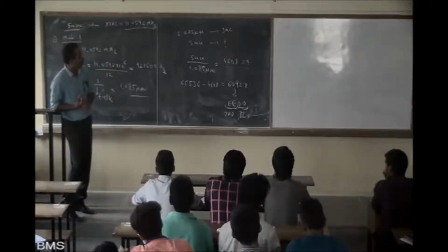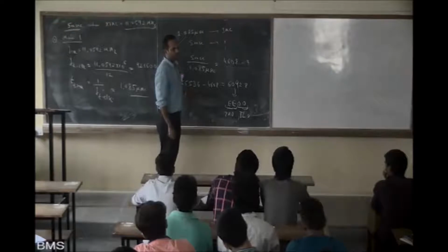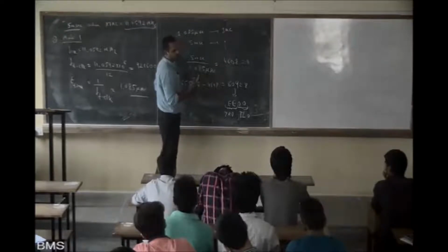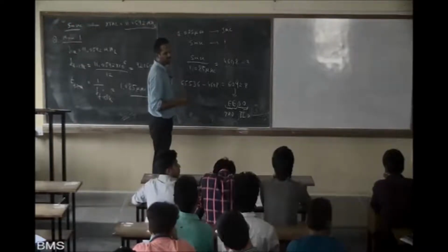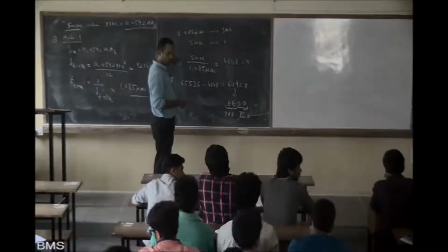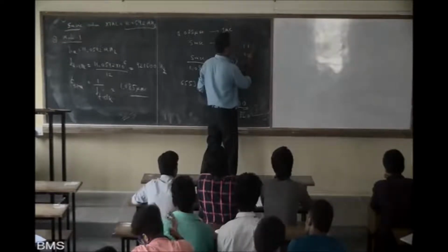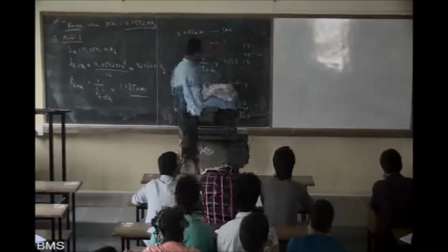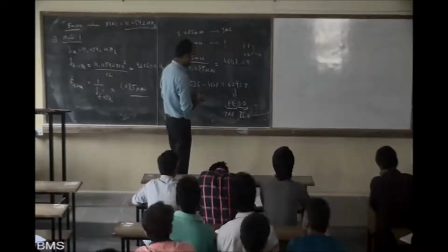That is why we have considered here 65,536. This will count full, 00 to FF. Next it will start at 00. What you are saying is it should be 4609. Yes, once it goes from FF to 00, then TF will be 1. So you are saying it has to be less than this value. I don't think so.